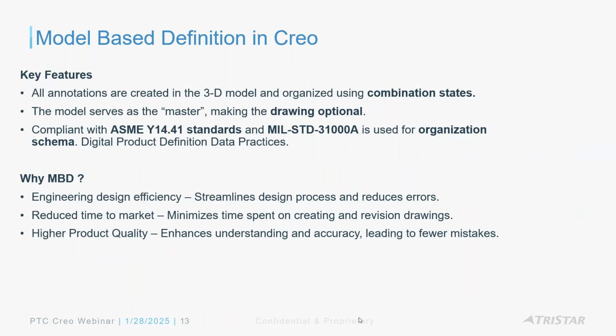Okay. So with that said, let's talk about Creo now, right? So with that little high-level overview, on the Creo side, all we're doing is taking advantage of this thing called combination states, which some of you may or may not have used. It's very helpful in the assembly environment. Those who are not doing MBD, you may have used combination states quite a lot in assemblies and leveraging that in your 2D drawings.